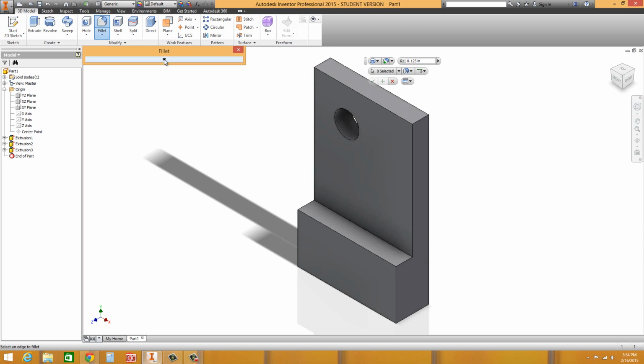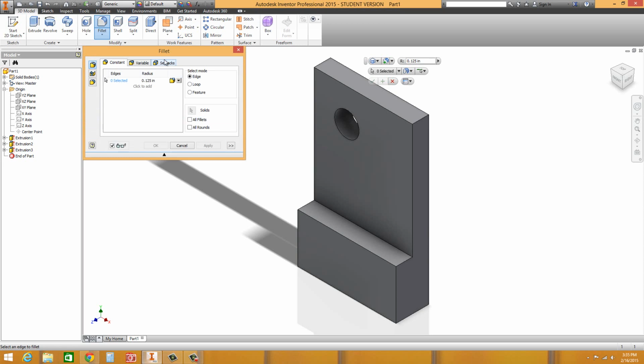And again, because we're novice users here, or just beginners I should say, click on this little arrow to give you some of the more specific options versus the quick launch, which is very nice, but in this case I just want you to learn a little bit more here. Let's set the radius to 1 inch. Now take your pointer and get to this edge.